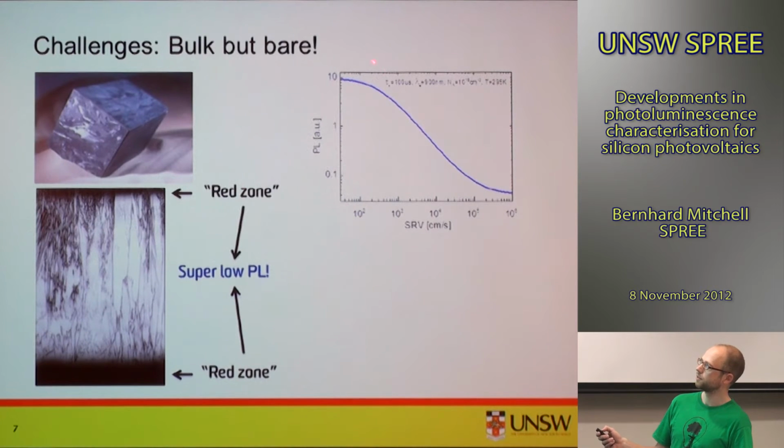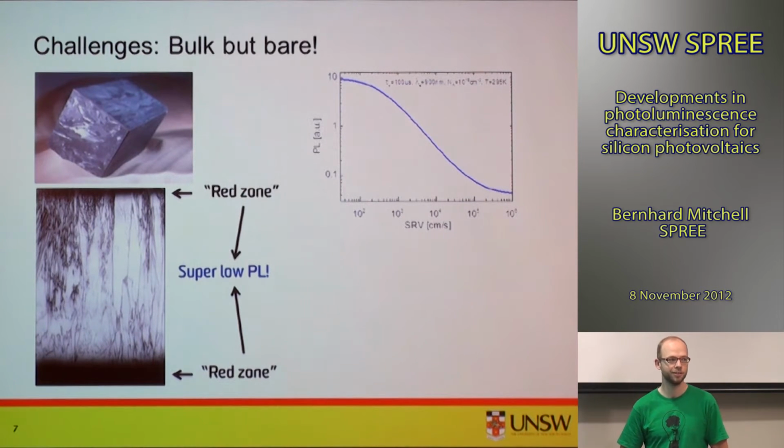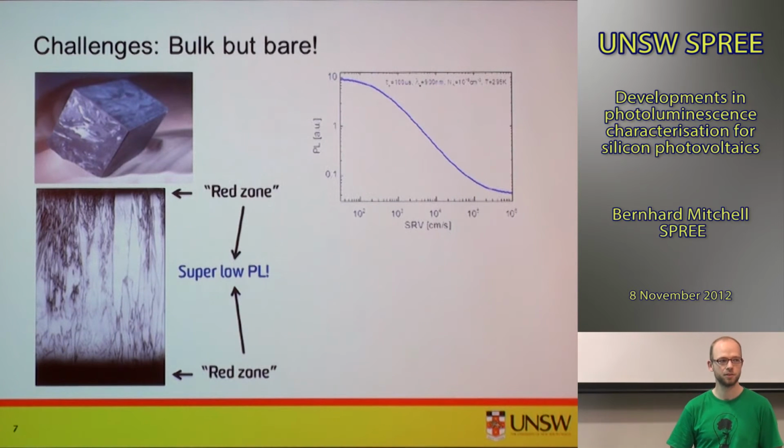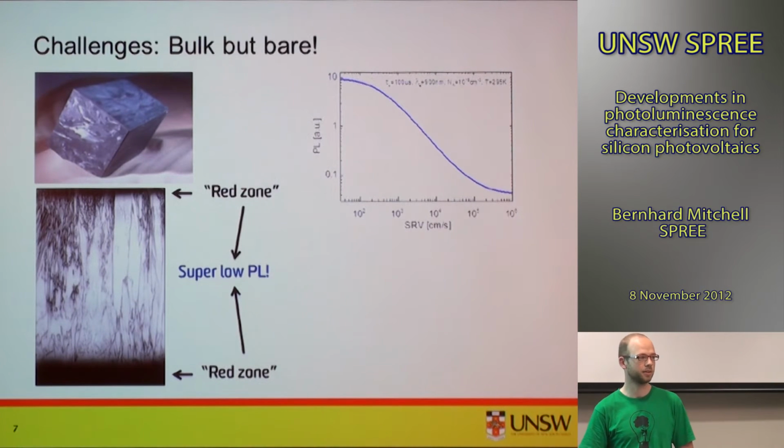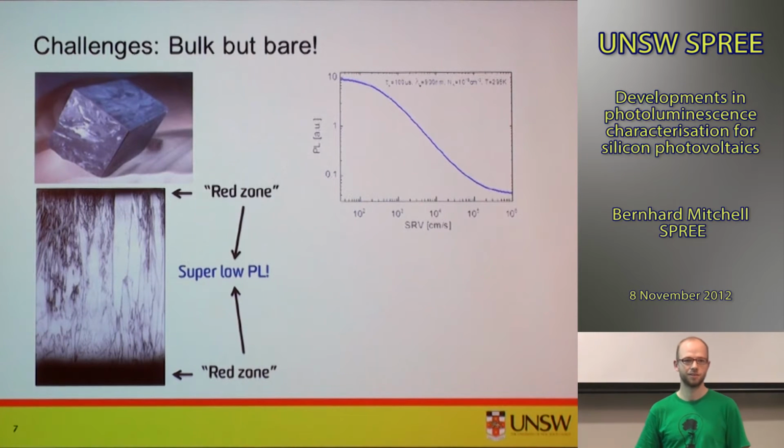If we would passivate the surface, we would be able to have PL intensities which are more than 100 times higher. And this is a very good example of how it's actually also happening on silicon wafers, that we can have a much higher signal if we passivate surfaces. The calculation would give slightly different numbers, but that's the same ballpark. We can increase the PL intensity by about 100 times if we passivate the surface.